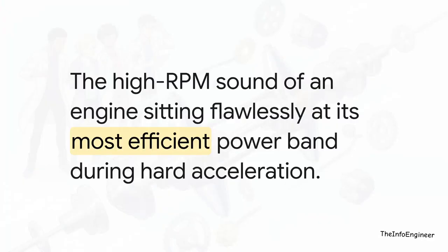But there is a catch, and it has everything to do with how we as humans perceive speed. You know, drivers often complain about an elastic feel and this loud droning sound when they floor the gas pedal in a CVT car. Because the transmission is doing all the work of changing speeds while the engine RPM stays completely flat, the car just sounds different. But we really need to reframe this. That drone you hear? That is literally the sound of perfect, unbroken mathematical efficiency. It is the sound of the engine sitting flawlessly at its peak power band, while the infinite ramp of the variator catches up to the wheels.